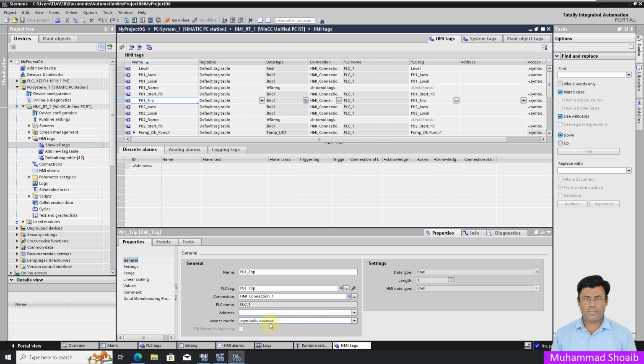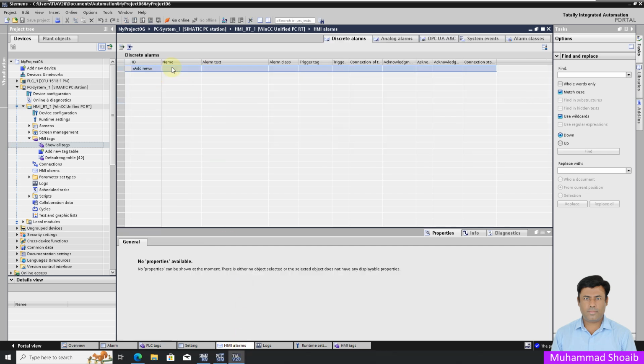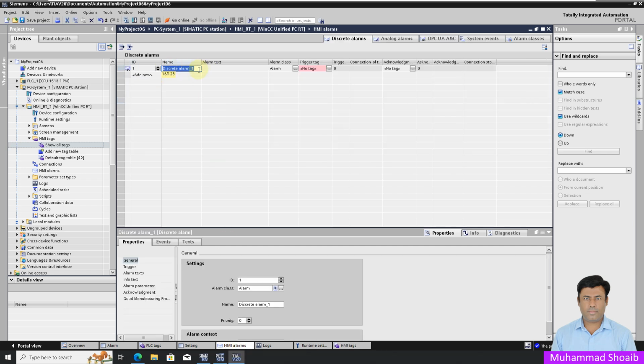Okay, so I will use this way, and here I will write the name. For example, I will write E01 trip alarm ALM, and here I will write the description: pump 01 trip alarm.